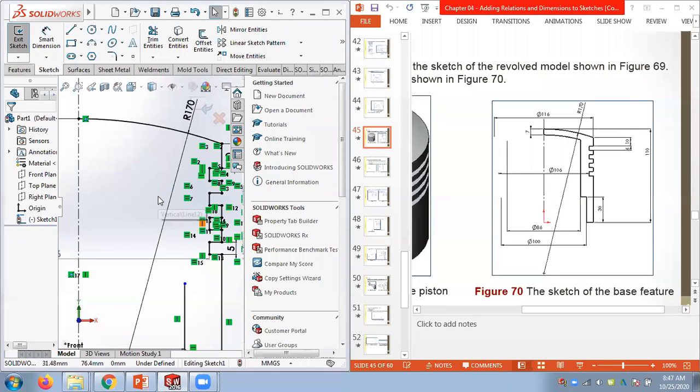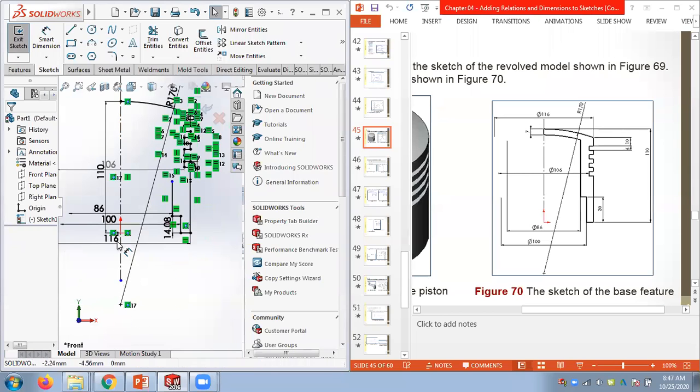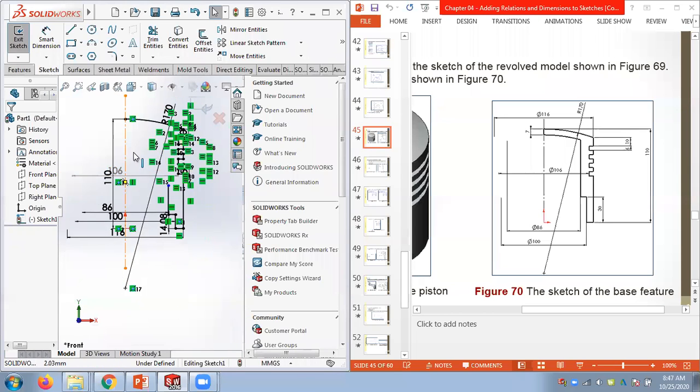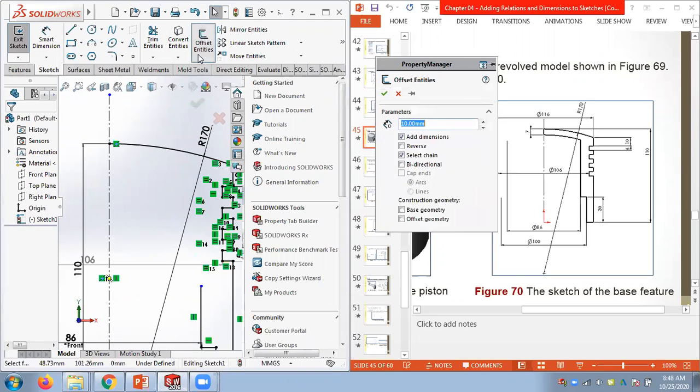So that's how I took this arc shape here. So I gave this point 110. This is obviously coming from the lines, and 170 given, and this line and this point should be coincident with each other. So it's coincident. Then we can offset this line by arc by 7 units. So I will offset that one by 7.